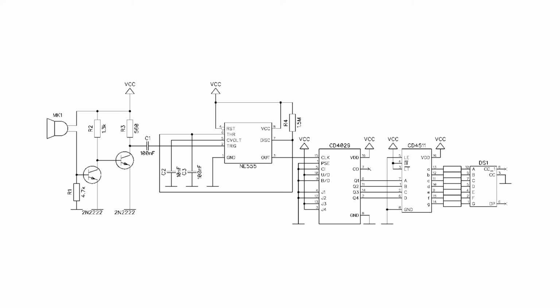Outputs marked as Q1, Q2, Q3 and Q4 are used to represent the counted number in binary form. The rest of the pins were connected so that the counter counted forward, incrementing the value. It showed us the number in the form of BCD code, counted from 0 to 9. The 4-bit code is then transmitted to the CD4511 decoding system. Its task is to interpret a 4-bit value so that it can be displayed correctly using a 7-segment display.